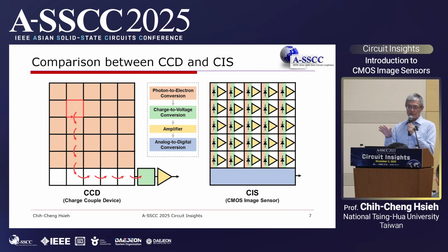The operation theorem depends on high voltage biasing and a high electrical field to couple the charge on the different pixels. So if you want to read out the charge on this pixel in red, you need many charge coupling and transfer operations until it reaches the separate readout circuit and is sent out.